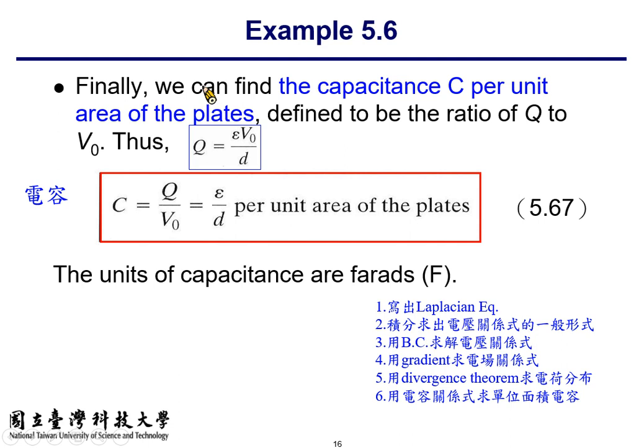So for companies specialized in manufacturing surface mounted devices, what can they do? If the capacitor size is limited, you can substitute a high permittivity material within that space. Usually the relative permittivity of plastic material, epsilon R, is on the order of 2 to 4.